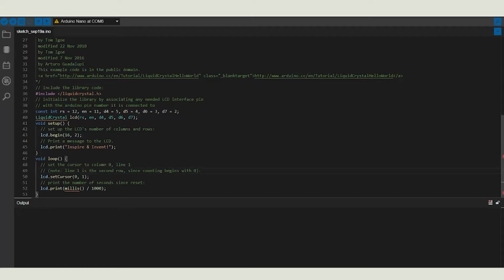So, how do timers work in the Arduino? Well, we can use this function called millis. It's a really important function. You will use it in a lot of projects. It's actually a timer of the Arduino, so it will time how long the Arduino is running, but in milliseconds. So, we don't want some thousands number there, that's going to be really confusing, so we have to divide it by 1000, because 1000 milliseconds is 1 second. So now we will have the number, which will be the timer of the Arduino running. And yeah, that's the whole code.